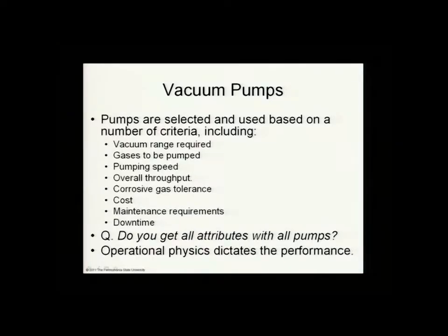We have to consider the pumping speed. How quickly do we want to be able to evacuate a region? That is, how quickly do we want to be able to control the pressure, reduce the pressure? We want to look at the overall throughput. Same issue, how fast do we want to be able to move gases in and out of a processing chamber?